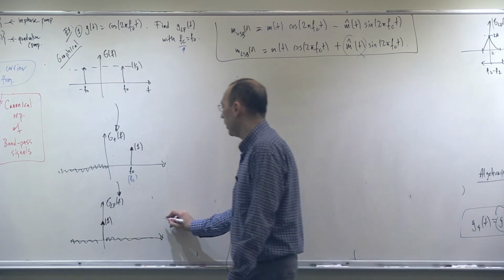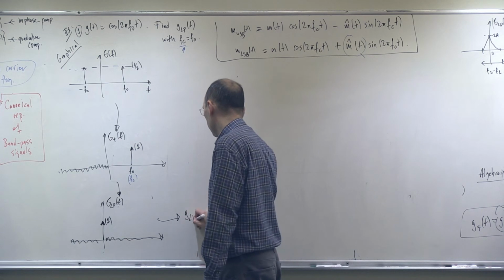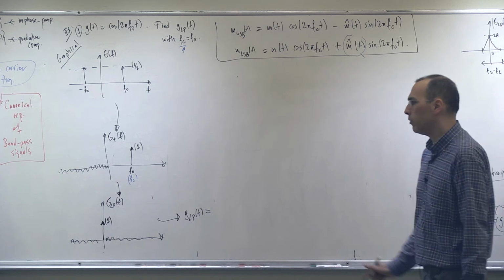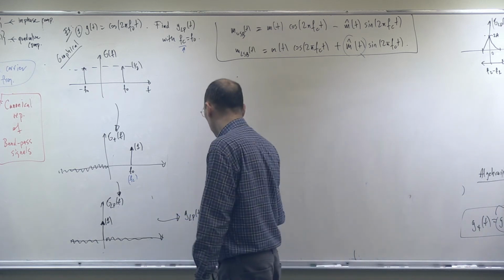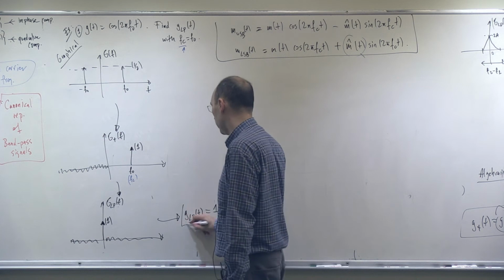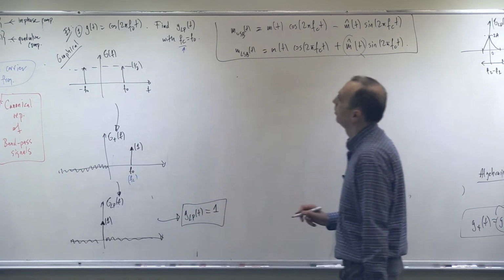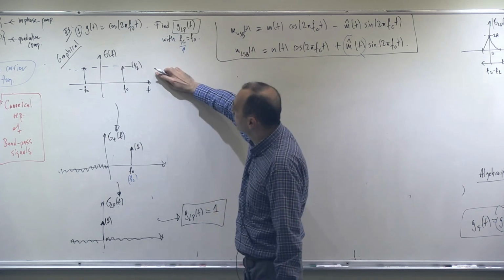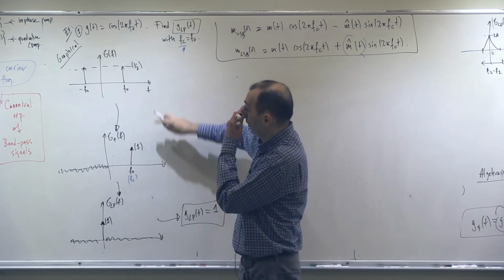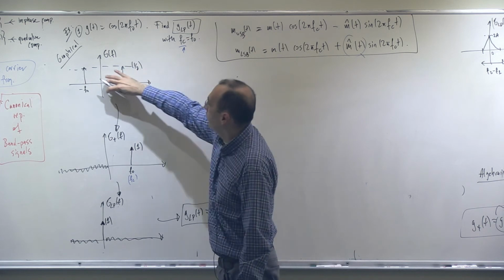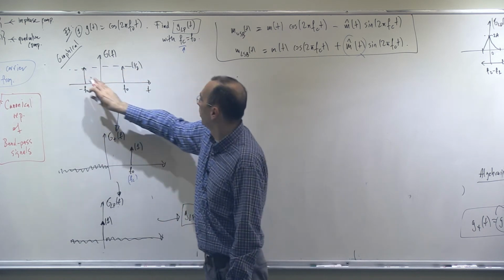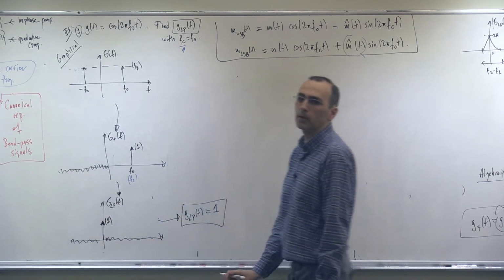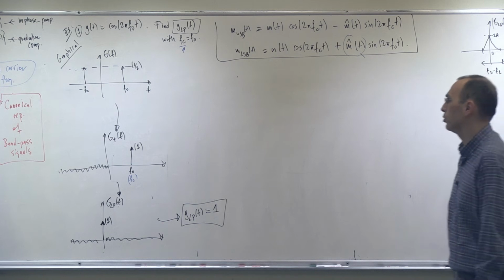So how about in time domain? Inverse Fourier transform of this is just constant 1. So this is the end of this case then, okay? Because it was find this with this. So the story is in 2 steps. The information bearing part is this part, wherever it is, because this is redundant. So I first null this part, then shift this, make it low pass. Low pass signal. That is the whole story.